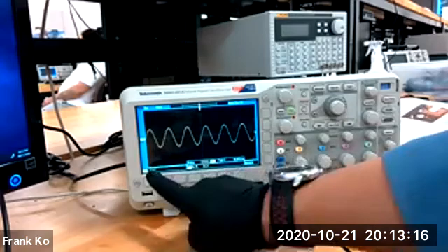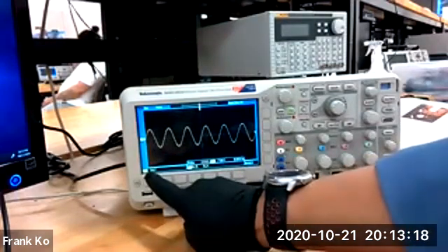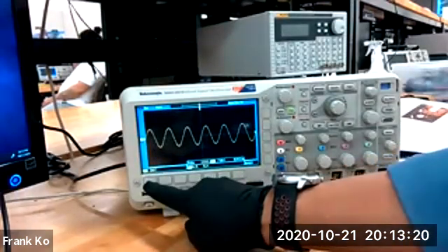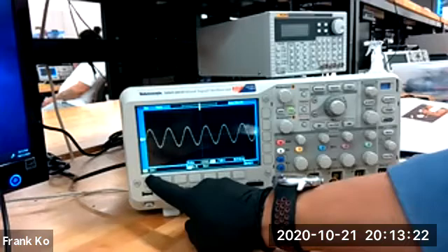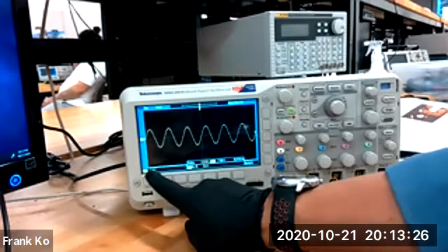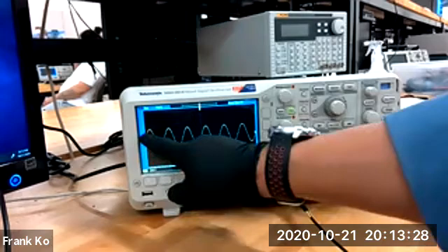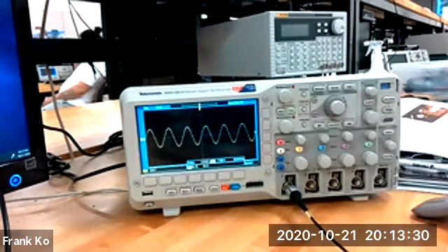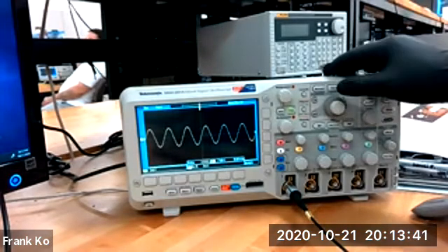And when you go to do so, what does your voltage scale say on the far lower left? 13.1. No, on the scale. The scale is 20 volts per division, yes? Yeah. Okay, so at 20 volts per division, you have a nice little waveform on the display. So far, so good? Okay. Now, that being said, you also can set up to do this.